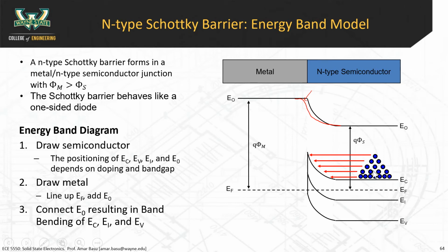And then one final point I would add is that in the band diagram, we also have the holes that we think about. In a PN junction, the holes also have a barrier here. In this case, it turns out that the holes actually don't have a barrier. The holes can actually go freely back and forth like this. Because if you think about this band diagram, below the valence band, as you know, in an N-type semiconductor there are mainly electrons up here, but there are some very few holes. Holes like to go up the slope. So if there were a hole down here below EV, the hole could go up this way. So the hole could transport up this way.